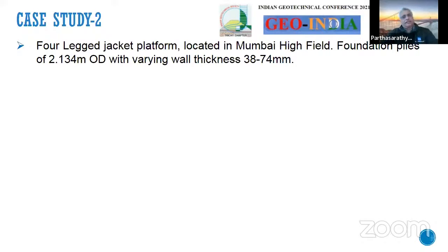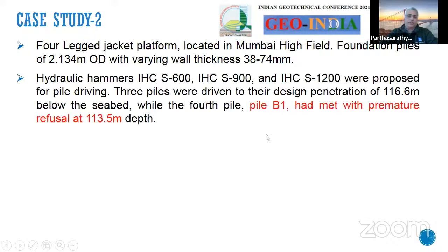Although the equipment was there on board, technically I was curious, because the region where this jacket was installed is also known to have very wide lateral variation. So in real time, I was getting updates that the piles were driven. The first leg was completed, the second and the third were very happy. But one morning, we got a call that the last pile was driven, but it refused 3 meters shorter than